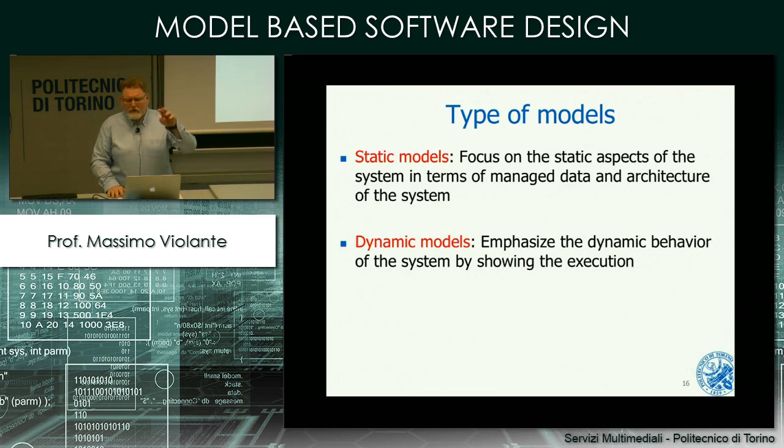We can have some blocks that are intended for interfacing with the sensors. Then we can have another block that is intended for interfacing with the CAN network. Then we can have another block that contains the application logic, so taking the inputs from the other blocks, it decides whether to make the call. And then we can have another block that is responsible for managing the modem to make calls.